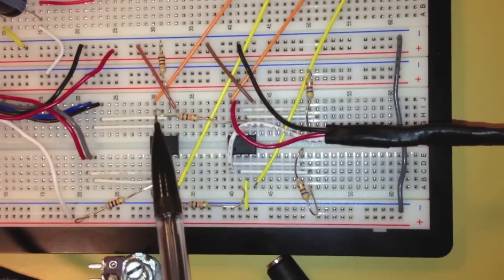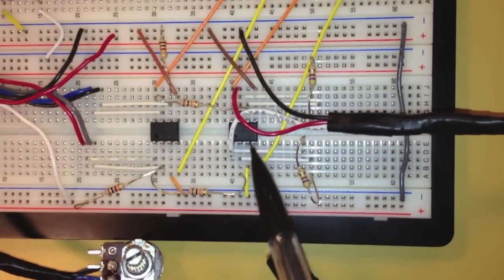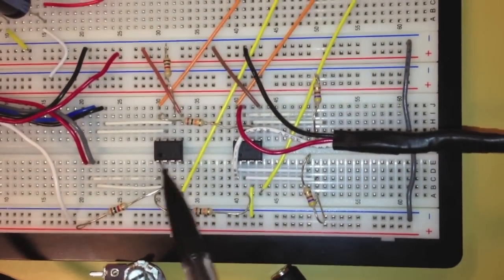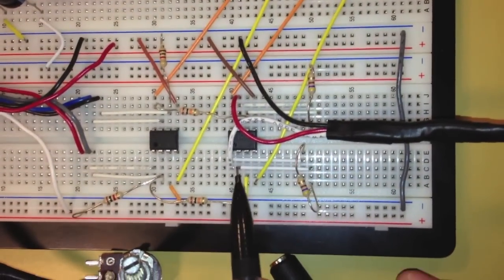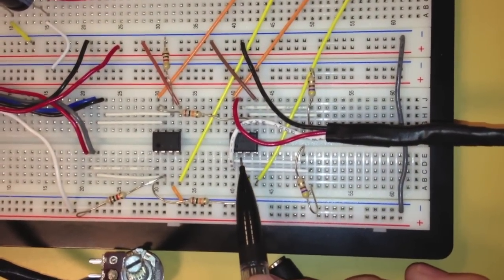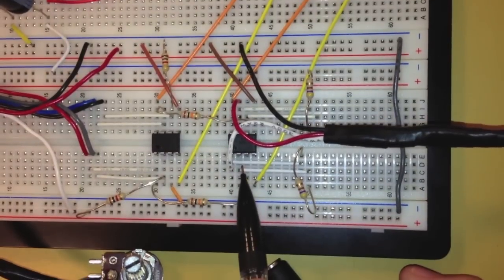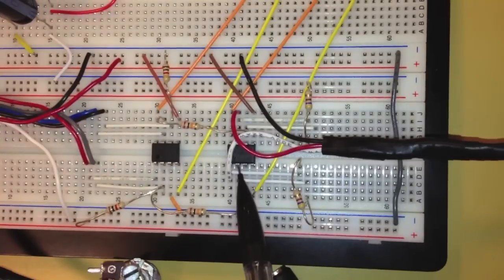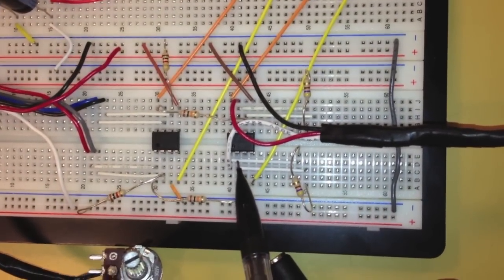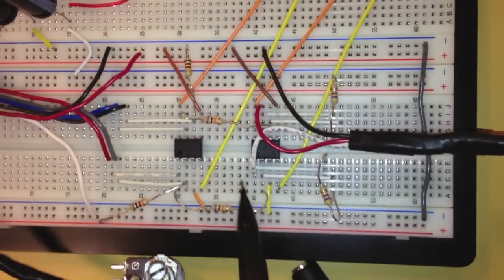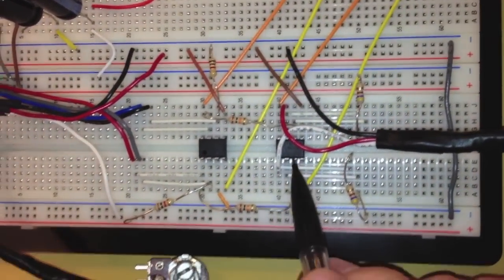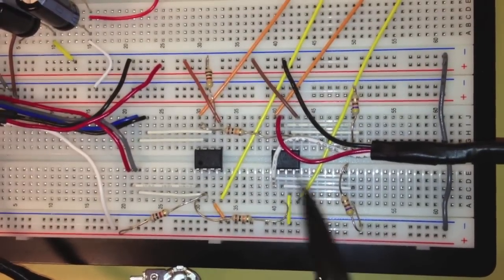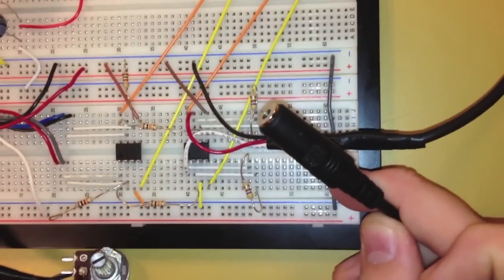And then from here it goes through this 10K resistor into the secondary stage amplifier. This one takes the inverted signal and makes it positive again, but it doesn't really amplify the signal as much as it reduces it, so we don't overload the speakers, and so it sounds much better. This part of the amplifier has a gain of 0.47. I'm sorry, it's 0.047. So between the two, overall, you get a gain of 2.35 before it goes to the output side of our amplifier.